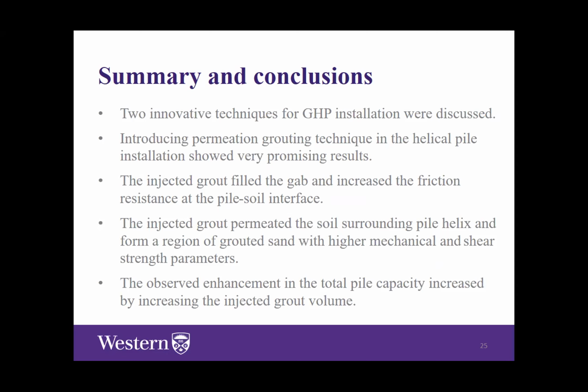We used variable injected grout volume and different grouting pressure. However, we observed that the creation of the grout sand bulb was not uniform. For some of them, we observed non-uniform shapes, which I believe is because grout always tries to move toward the easiest path, and the soil is not a homogeneous material.